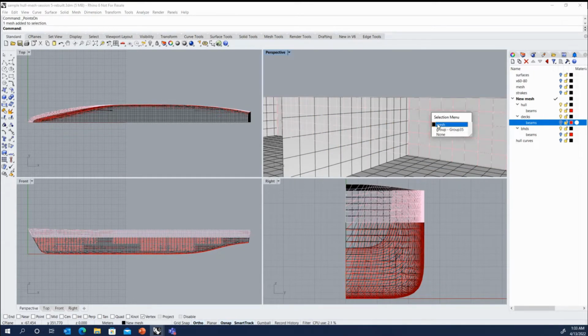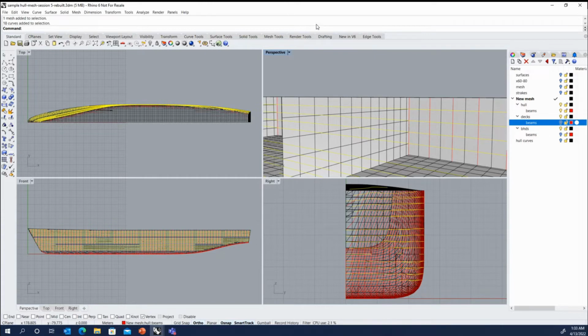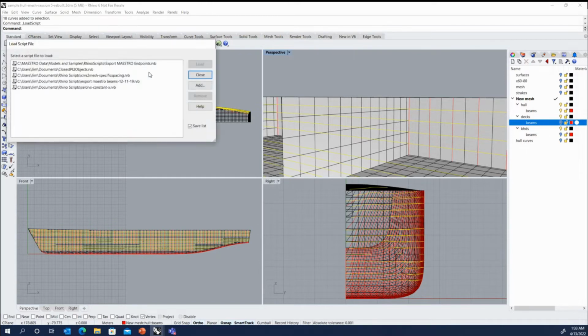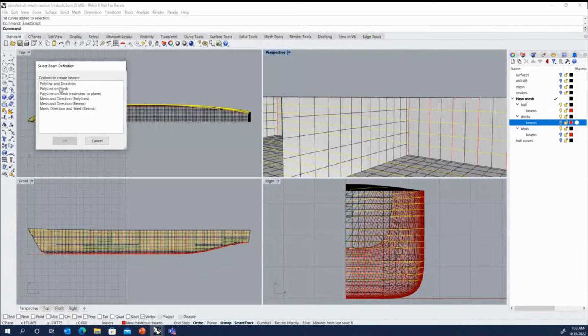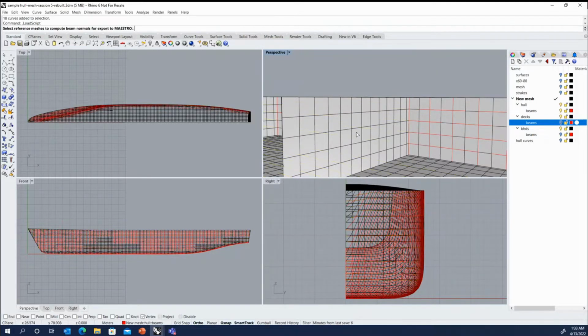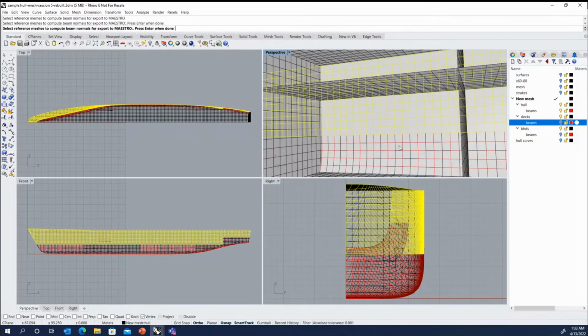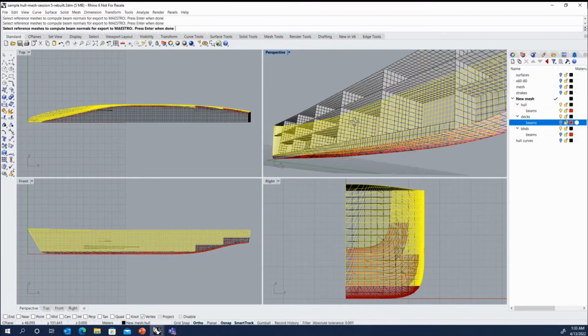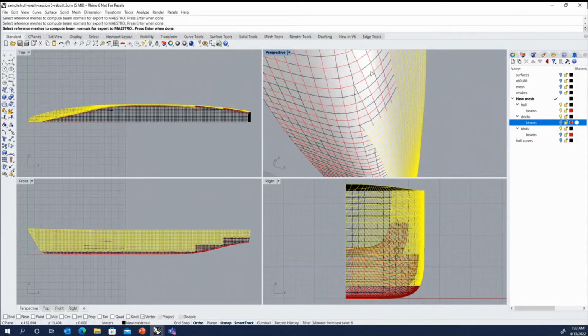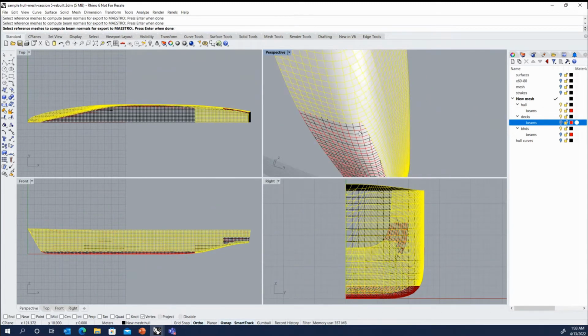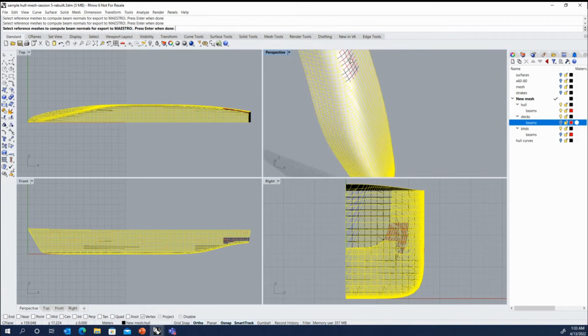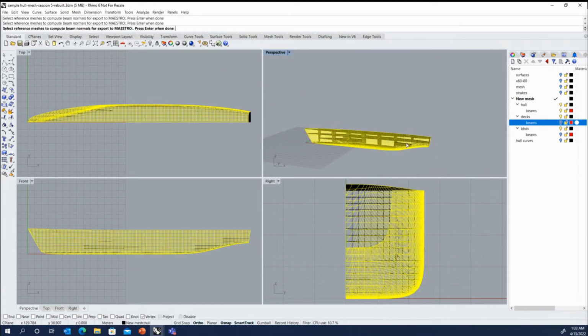So if we take these beams and run the script, and we say polyline on mesh, it will then ask us for a reference mesh. So we want to pick a mesh that has those beams, and I think I had all of the beams grouped in there. It won't hurt if we select too many meshes. This is just the meshes it's going to look into, so it's not a big deal if there are extras in there.